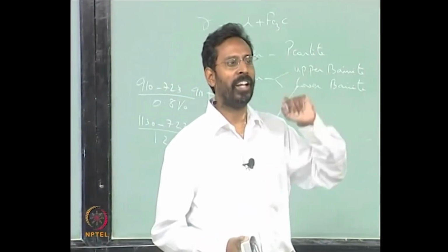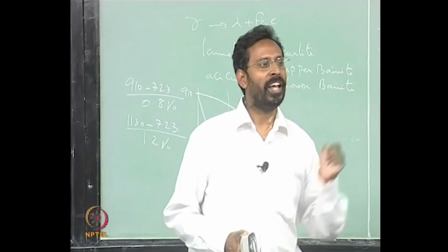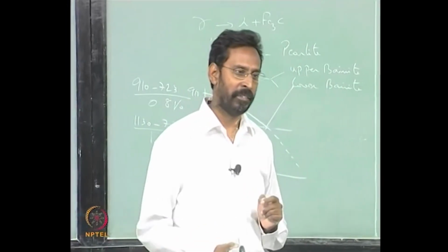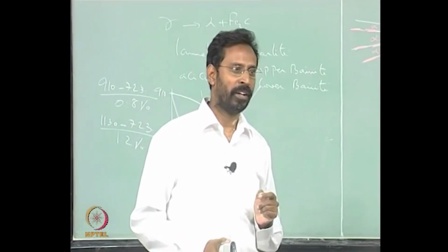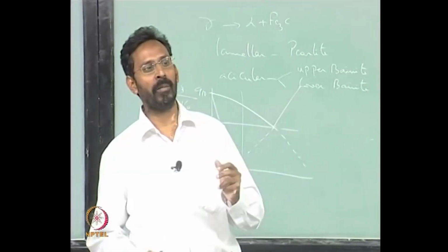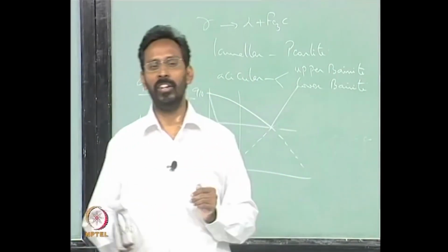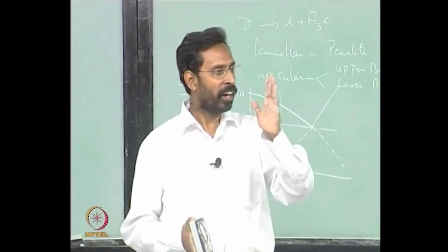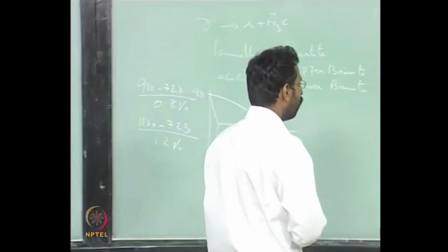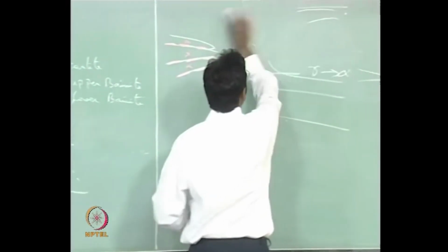Because when you take a high carbon steel, there is pro-eutectoid cementite coming out, and the moment it comes out, it can nucleate pearlite. So there are always issues like that. That is why, interestingly, if you have ever seen the TTT diagram,